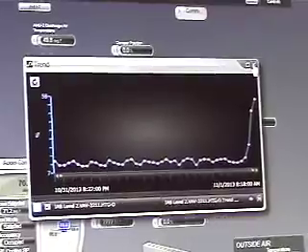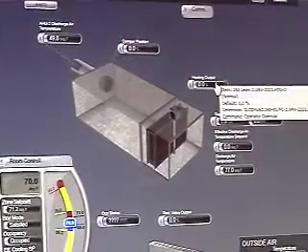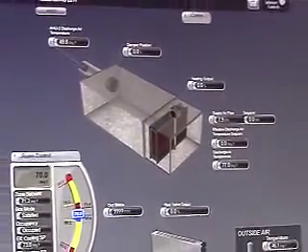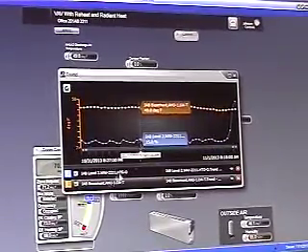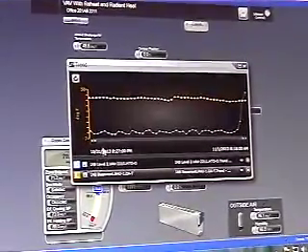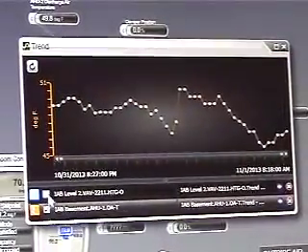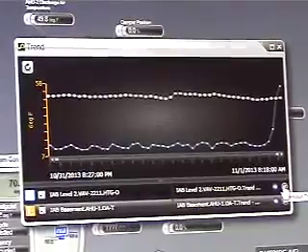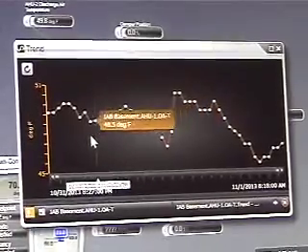Another cool feature that you have the ability to do is also to overlay additional trends on it. So I've looked at the one, and now if I just grab another one, we'll just look at temperature. Now you see that it's added another one overlaid on top of it. I can either hide it or add it, but it gives you just another ability to troubleshoot the points in the same reference of time. And if I just want the one trend back up, I just remove trend and we're good to go. So whatever is physically inside the NAE before it dumps to the repository, you can look at it through the trend viewer this way. Anything past it, you can still use a trend study or use a trend viewer to actually pull trends from the server.